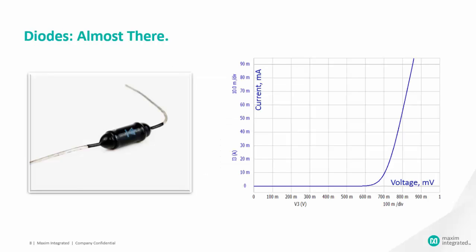The diode is the very first small, inexpensive electronic structure that provides a relatively stable voltage, that is, the famous 0.6 to 0.7 volts between its anode and cathode when forward biased. As a voltage reference, the p-n junction is sometimes sufficient for simple designs, but its output varies quite a lot with temperature, about -2 millivolts per degree centigrade, and it's also highly dependent on bias current. For example, a 600 millivolt diode at ambient temperature reduces to 400 millivolts at 125 degrees C. That's a 1/3 drop in voltage.